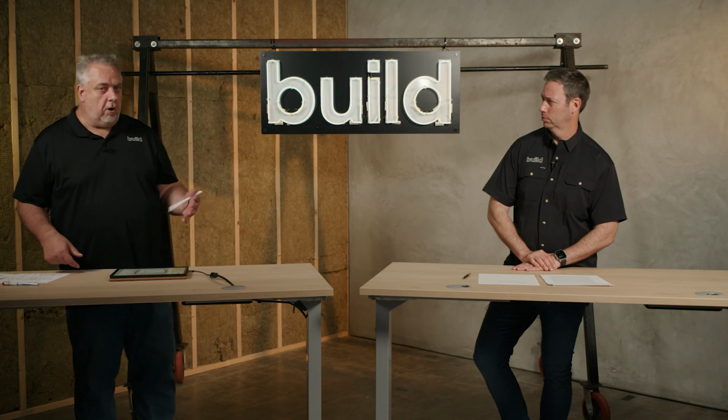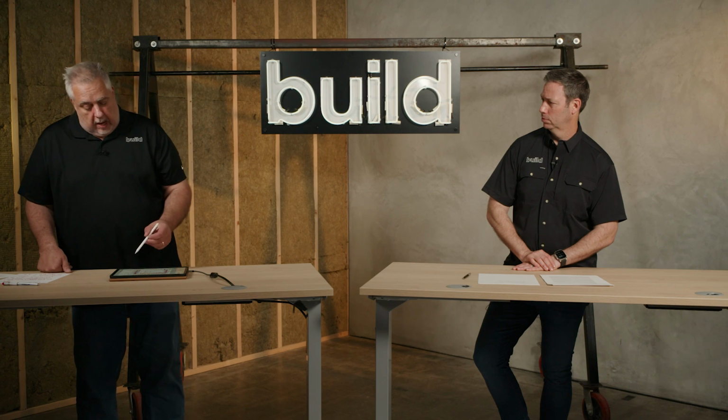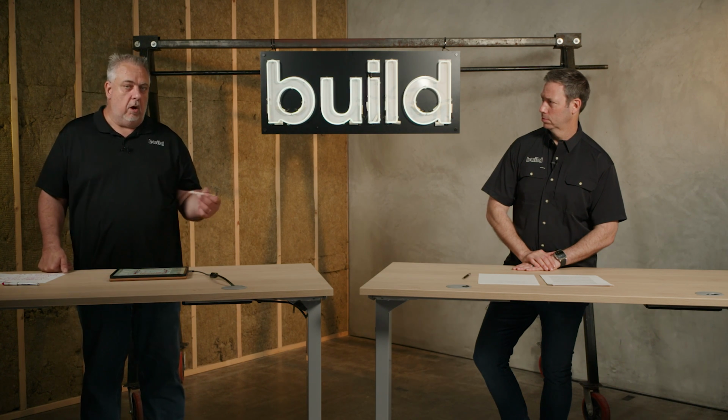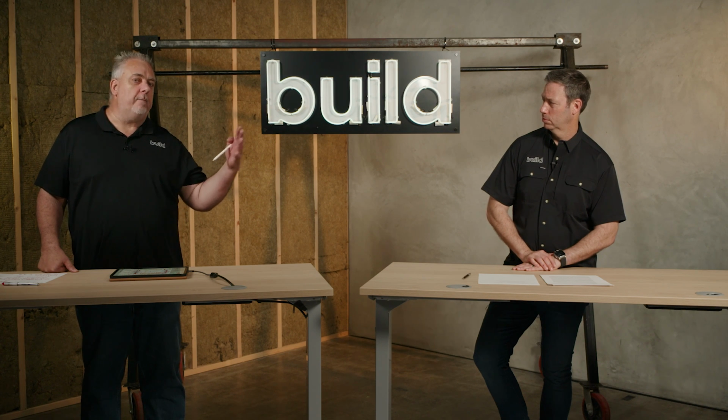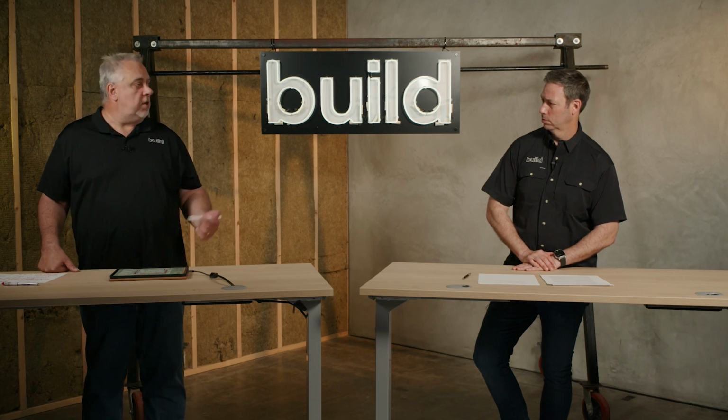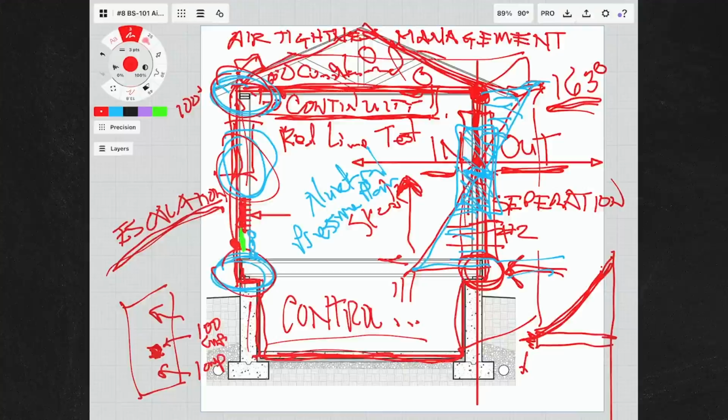And you sit there and you go, okay, what's happening? Well, at first glance, you might think, okay, well, it's got to be water bringing it, but it's not a water management problem. It's an air tightness problem. Because in that 4-foot overhang, you can imagine, a person can crawl through here, right? It's a pretty big opening. But when we look at the materials, there was a slate roof. The slate roof was over paper, over plywood, and you had the exterior wall here.